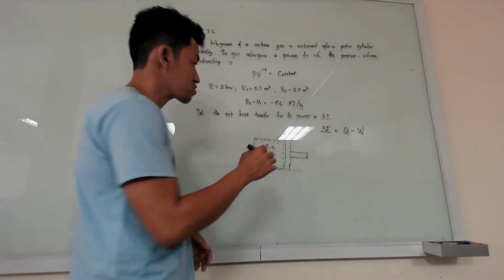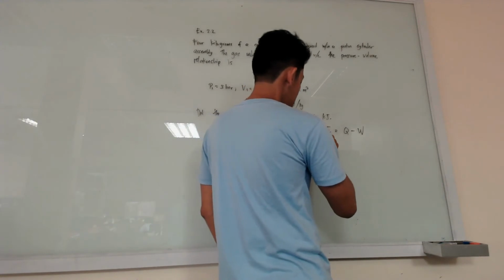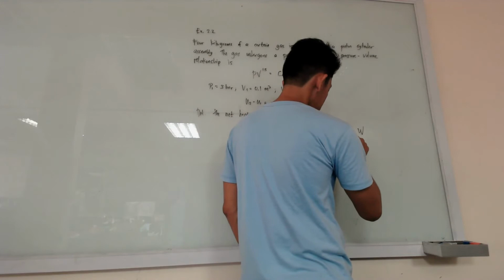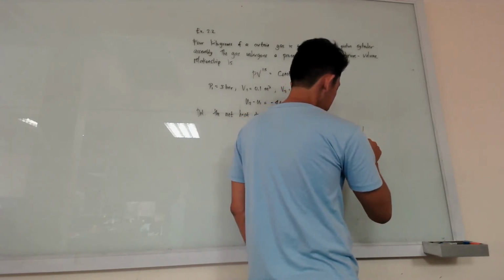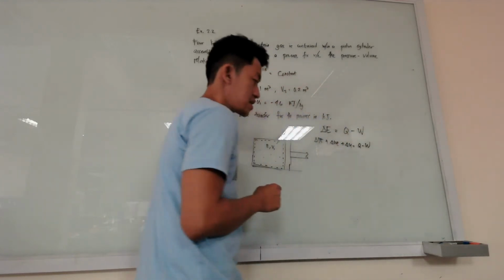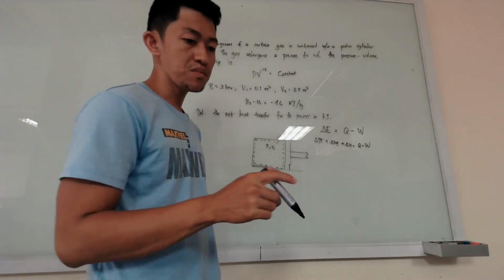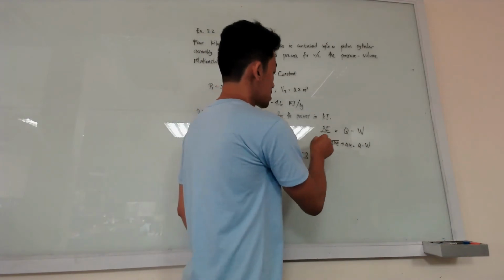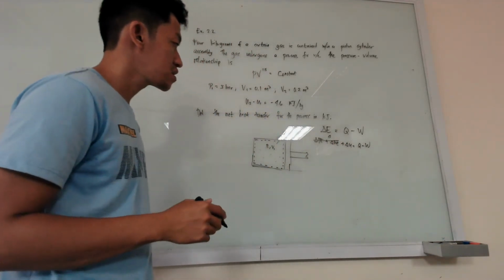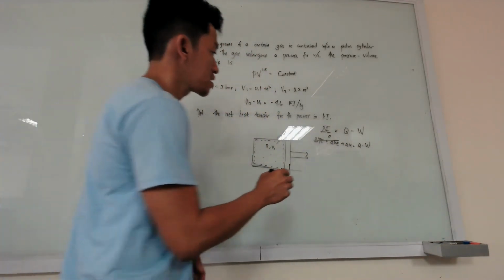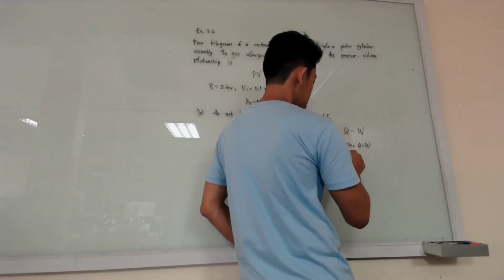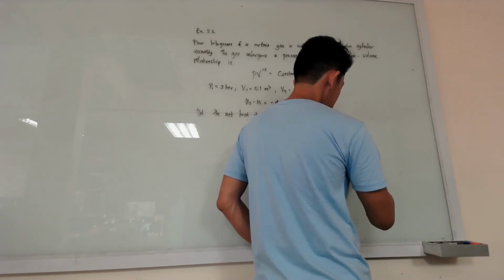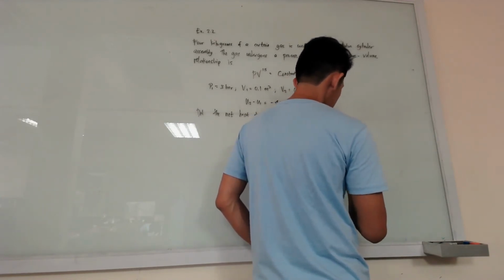Okay, so your energy is composed of change in potential plus change in kinetic plus change in internal energy. Okay? But in the problem, the change in potential and kinetic is negligible. So, zero, negligible. Therefore, this Q is just the change in internal energy plus work.